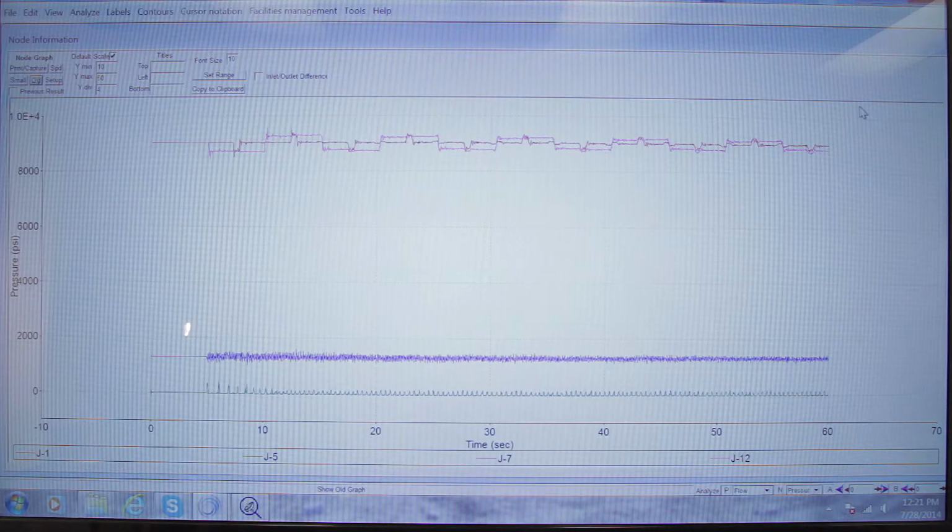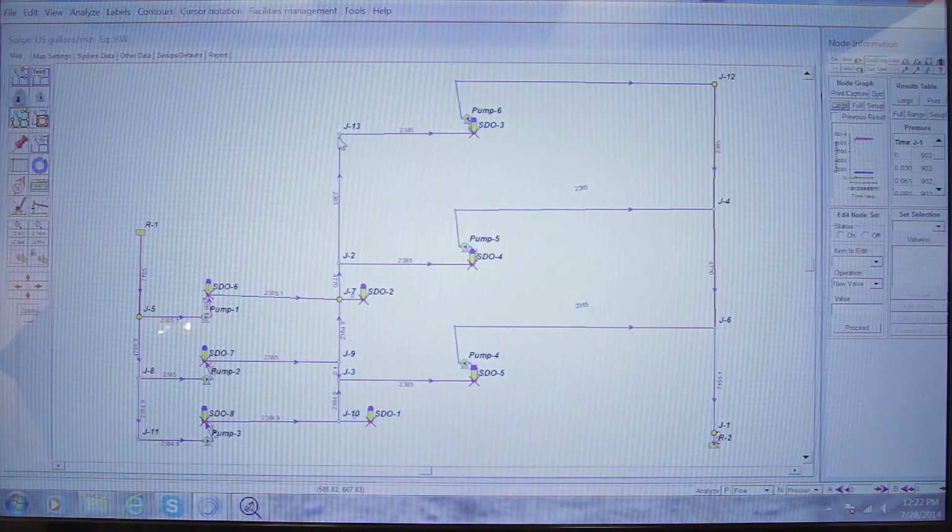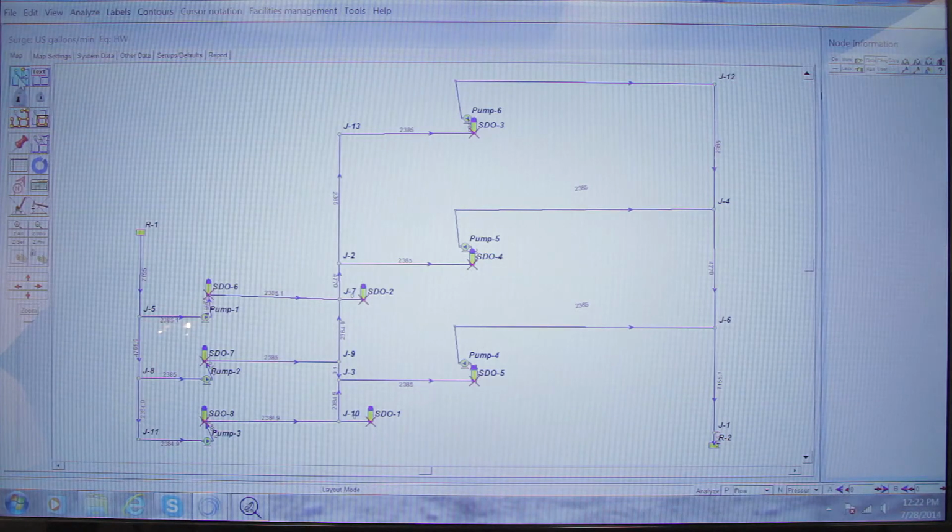So again, in this model and simulation, we're trying to control the pressure and flow. In this case, in the model, we have our booster pumps feeding the injection pump. And again, if the injection pump trips, we have low pressure piping interfacing with high pressure. Again, having a check valve there and that check valve closing rate. What happens when that valve slams shut? We're going to have an upsurge, and we can simulate it, looking at how that pump trip in the high pressure piping affects my low pressure piping.